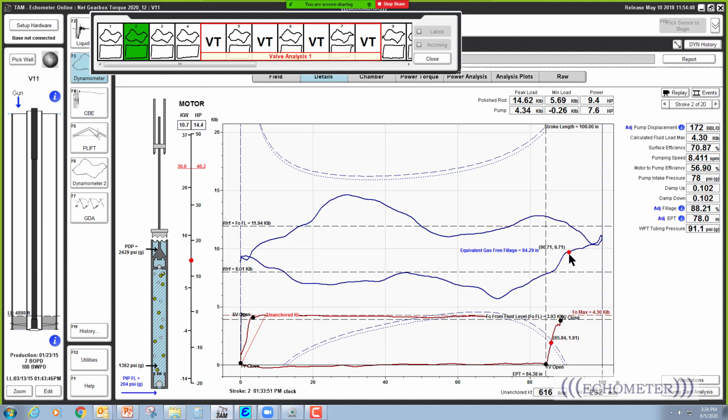And then when I come back on the downstroke, when I get to right about here, that's where the peak torque on the downstroke occurs. And to me, that provides information. It lets you understand the torque loading by looking at the kW. It's the same as net torque loading. We're looking at the surface card and the pump card and using that slider.